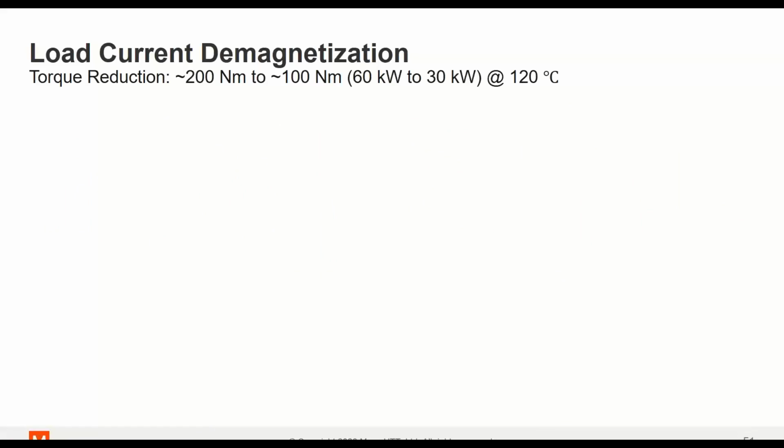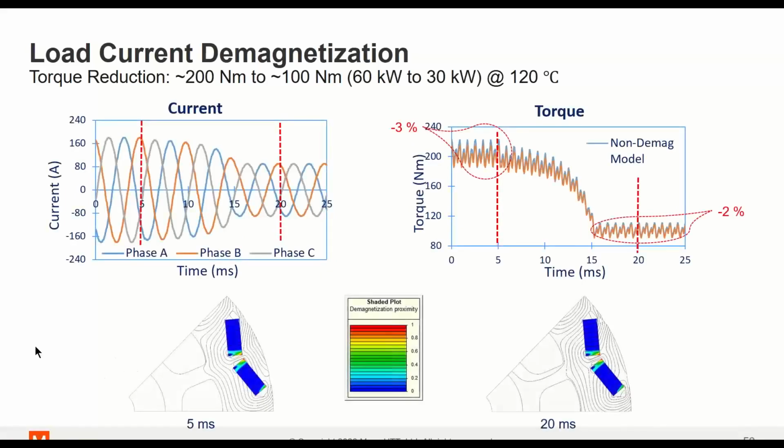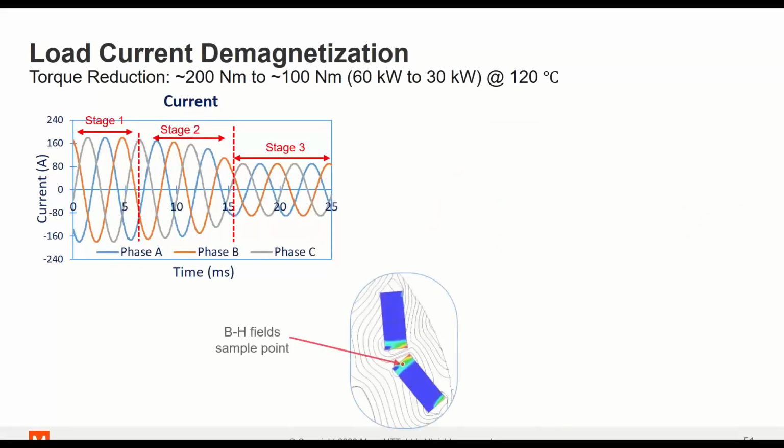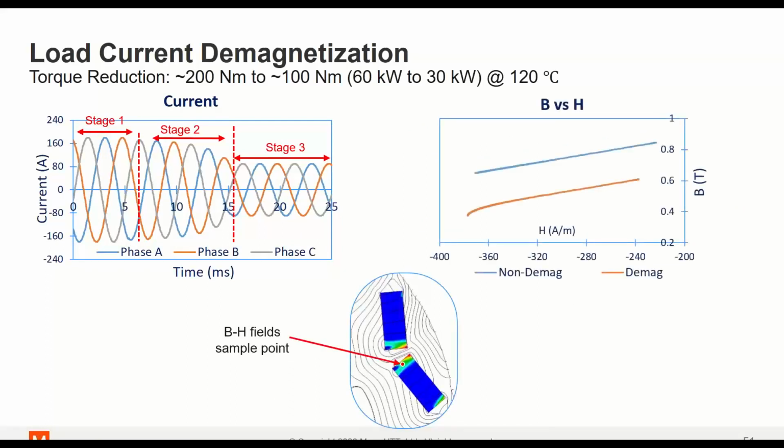And of course, let's check the magnet characteristics at the same sampling point that we have here at the center of the magnets. When the magnet recoils at the lower characteristics, it's a good indicator that the permanent magnet is demagnetized from the 3 sections.